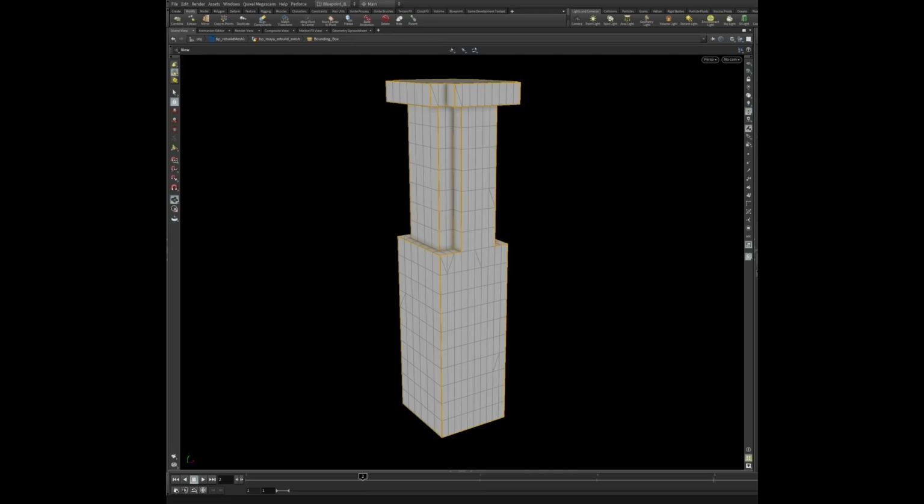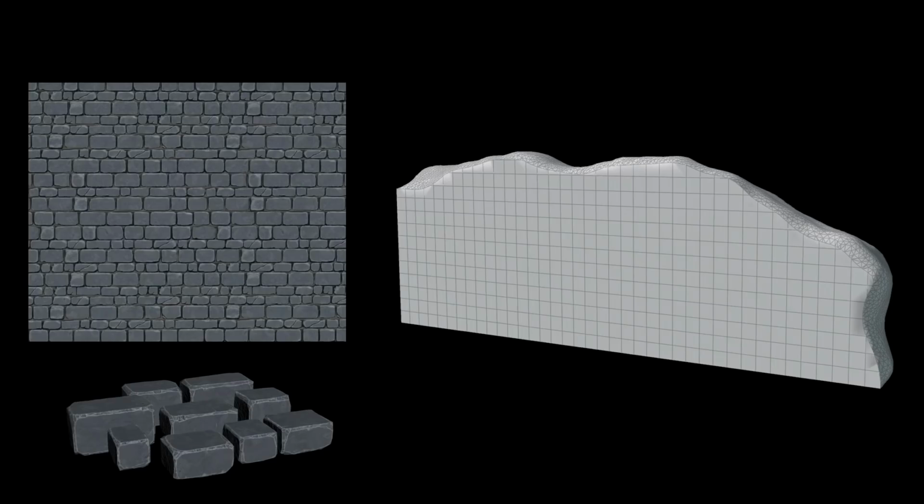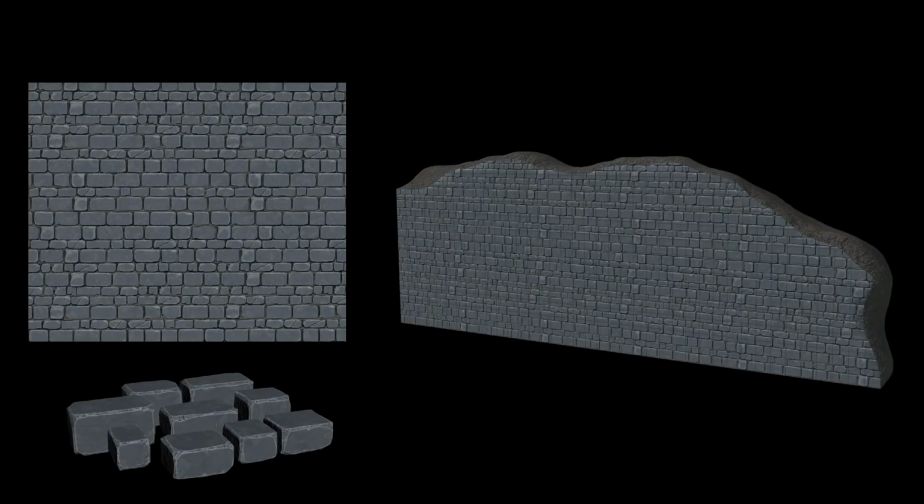Then I group all of the hard angle points, and run a dissolve to get rid of all of the interior geometry. Then you divide it and you're done. That's really like a 12 node setup right there. It really is that simple, it's not much more complicated than that. Obviously, if you get more complex geometry, you have to do more stuff to clean this up and address different solutions. But it works pretty good in that case.